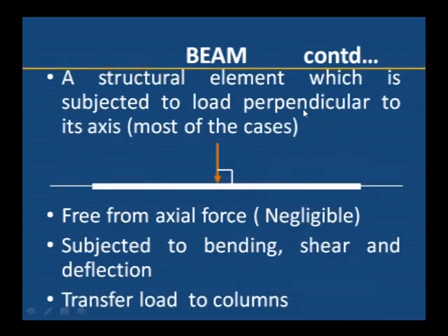A beam is a structural element which is subjected to load perpendicular to its axis. Here we can observe the load acting perpendicular to the axis of the beam. It is free from axial forces; only transverse forces act on the beam. It is also subjected to bending, shear and deflection. In strength of materials, we will study how to calculate the bending moment, shear force as well as deflection.